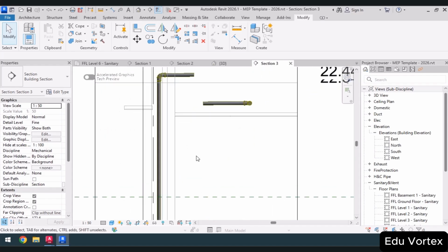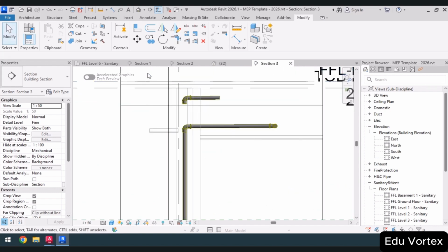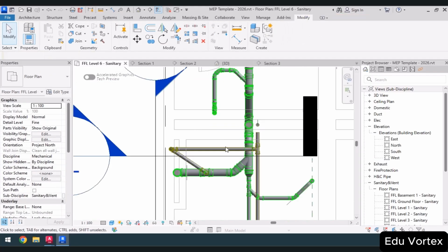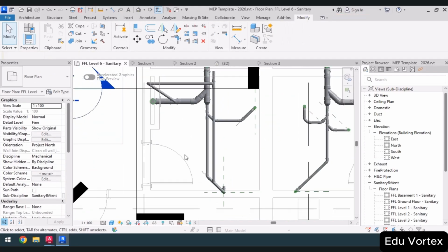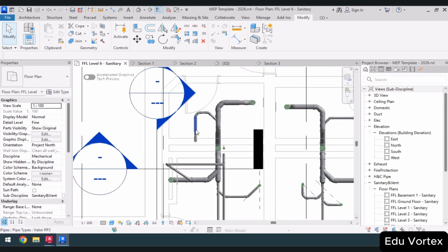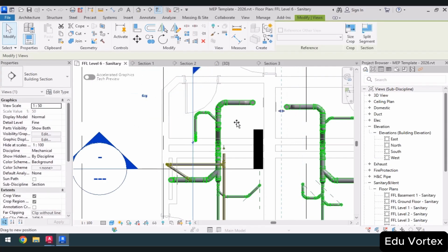For now, I will delete them instead. I will trim this connection. So let's check if everything is correct with these system types and connection positions after connecting them. Now that's connected, we delete this part and return to the plane where this section was drawn for the wash basins first. So let's gather this area a bit by right clicking and going to view.